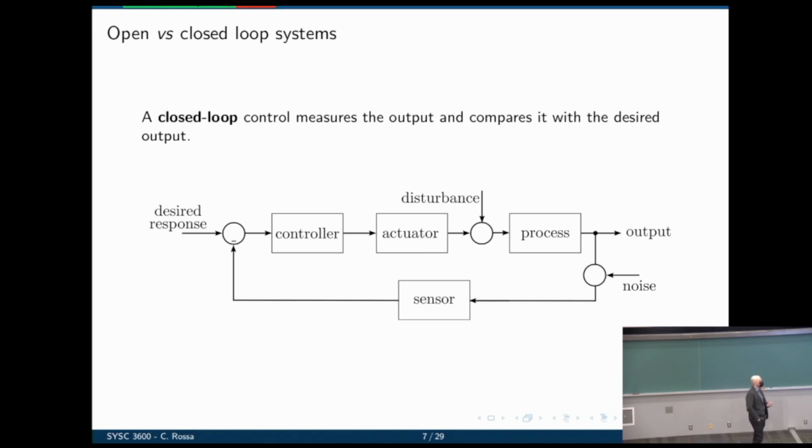What does that do? Well, now we are taking actions not based on the absolute speed of the car, but based on how far we are from the speed we want. Notice that little circle in the beginning there, the very first element, that's a sum. We are subtracting the current output from the desired output. In other words, we are calculating the speed error for the car. We are this far away from the speed we want. Now to get there, what do we need to do?